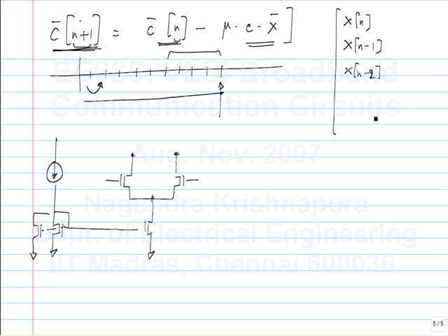What is the step size? Mu of each coefficient. And if I want to reduce mu, what do I have to do to the structure? No, not reduce the coefficient, reduce the value of mu. The update of each coefficient in any step is mu, right? How can I reduce the value of mu? Let's say I find that the value of mu is so large. Firstly, if the value of mu is very large, it can have non-convergence. But even if it is convergent, you don't want a case where, as I showed for the single coefficient case, it can be non-converging, but maybe it is not that bad.